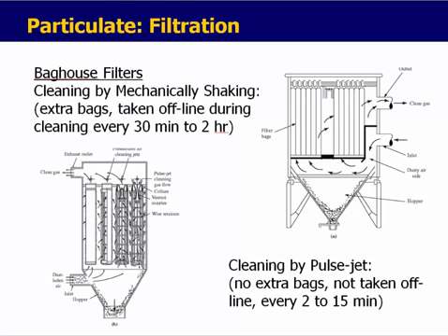This is the picture from your textbook of a baghouse. A baghouse simply has different filter bags, thus the baghouse, and air is pushed through these bags. So here you have your air that's going to push through that bag. It's going to have a lot of opportunity for those particles to interact with the bag, to be intercepted by the material, and clean gas flows out.